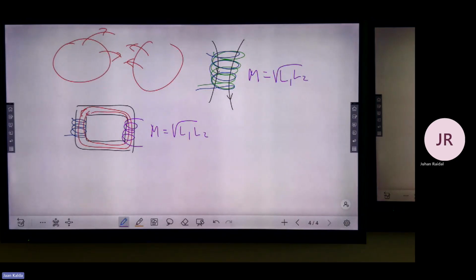But there is also a device which switches your electricity off if you have a so-called leakage current. Suppose some electric device has the phase wire connected to the body of the device, and you touch it, and then you get electricity subject to the voltage.